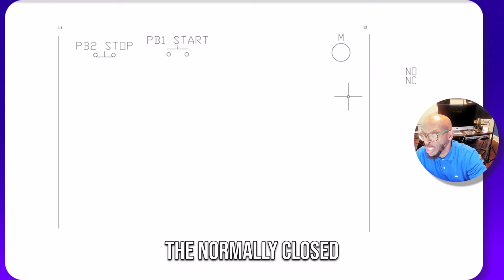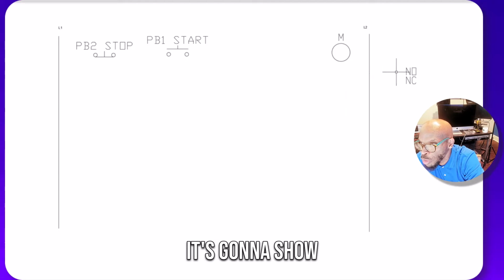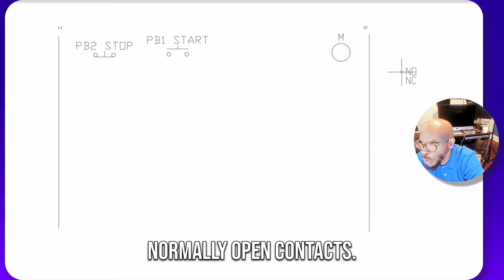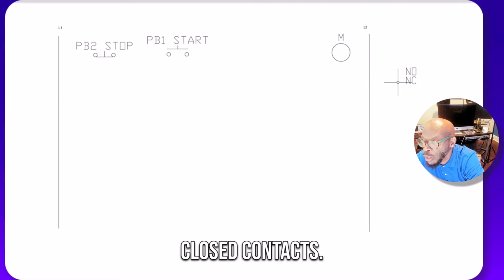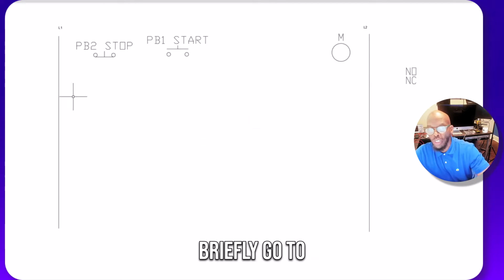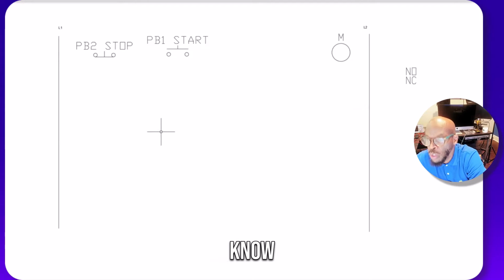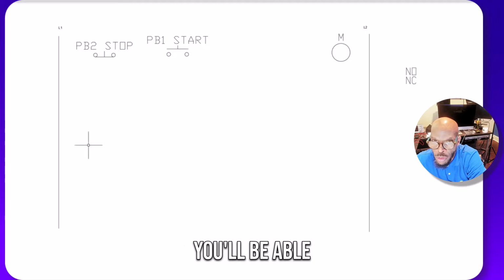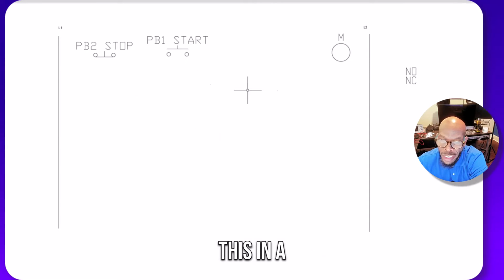The normally closed contacts are going to open. So wherever you see the numbers, it's going to show you how many rungs have the normally open contacts, and how many rungs have the normally closed contacts. So you can go to that particular rung, and you'll be able to troubleshoot your circuit doing that. We're going to talk more about this in a minute.